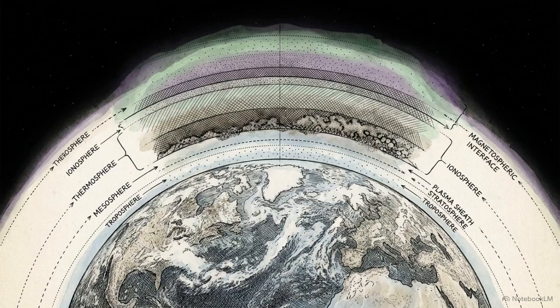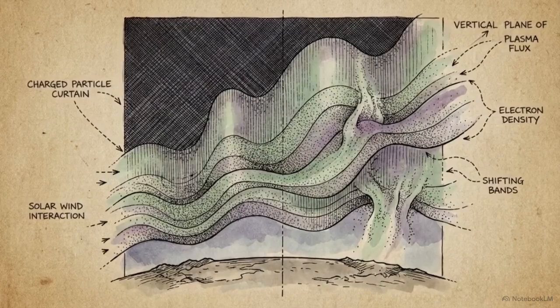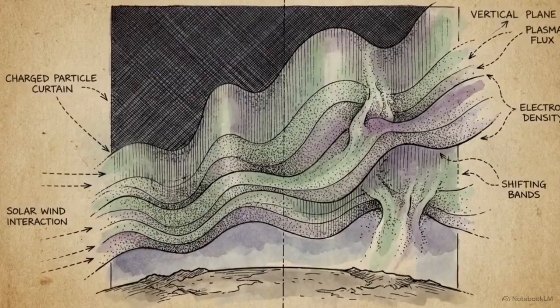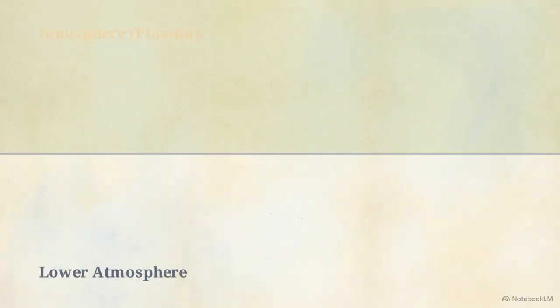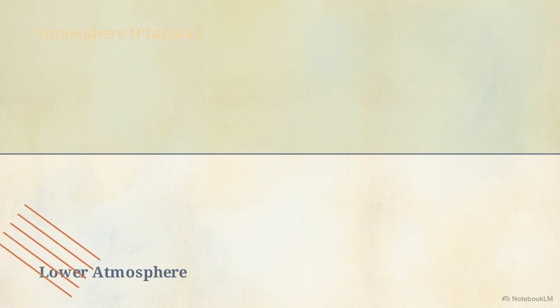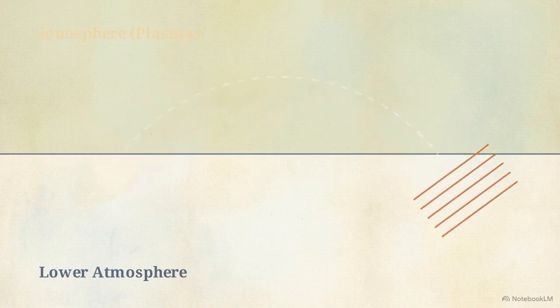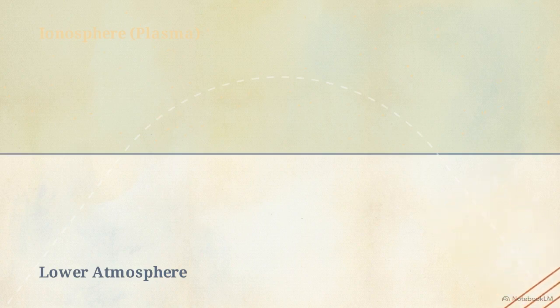This medium is the ionosphere, a stratified layer of plasma located between 50 and 2,000 kilometers above the Earth. Reliable long-range communication depends on the ability to predict the behavior of an invisible, continuously shifting fluid of charged particles. Refraction occurs because free electrons in a plasma increase an electromagnetic wave's speed. When a radio wave enters the ionosphere at an angle, its upper edge encounters these electrons first, accelerating and pivoting downward, forcing the signal into a curve that returns toward Earth.